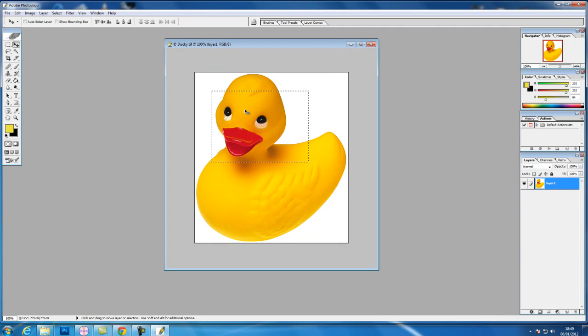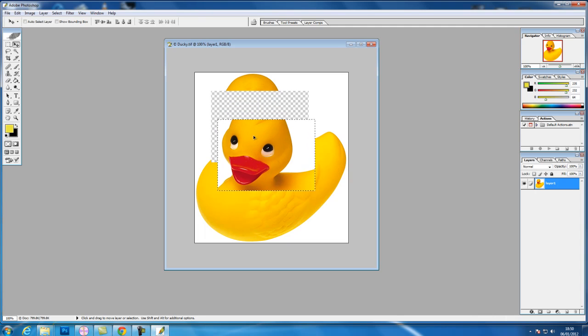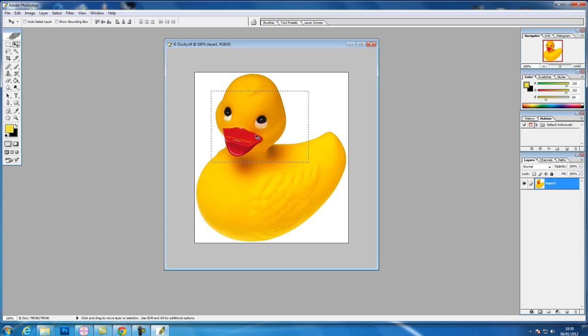You can see this by the scissors. If you see there is a little scissors icon on your cursor, you're effectively cutting and moving your selection set. To undo that, Control Z. To do multiple undos, it's Control Alt Z.